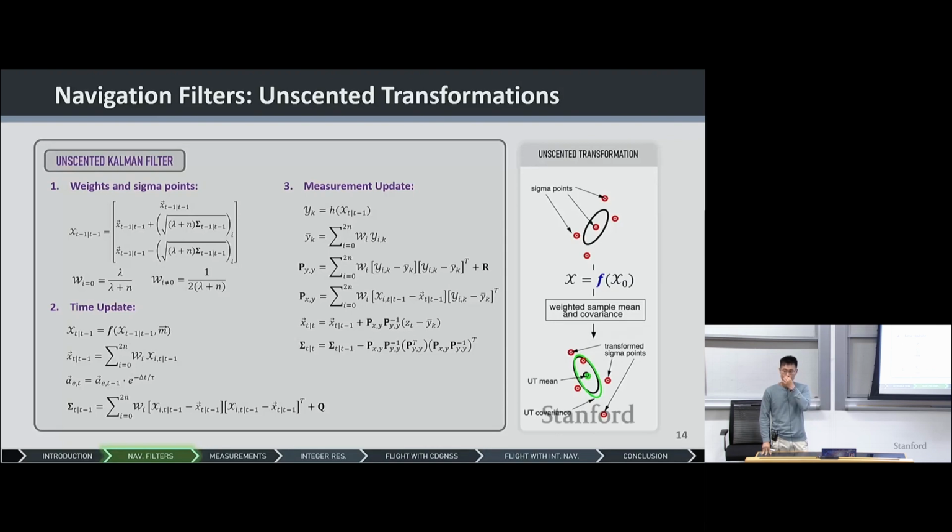But then the measurement model becomes more non-linear in order to go from the orbit elements to, for example, angle measurements, and there you need to capture the non-linearities, so you use the UKF. That's one of the reasons why, when we optimize for computational effort, we make that distinction.